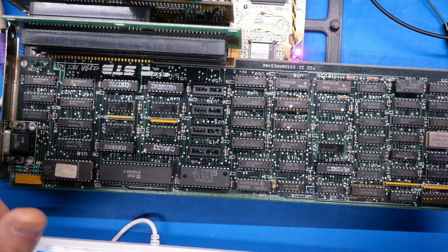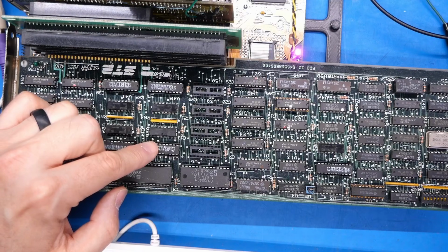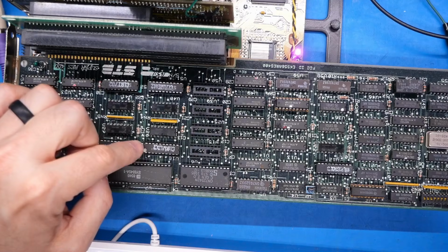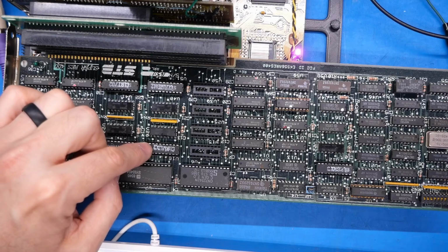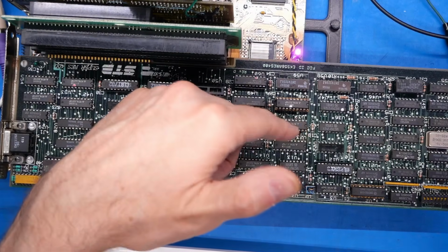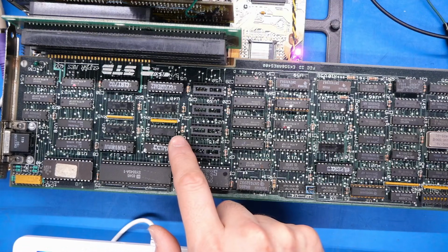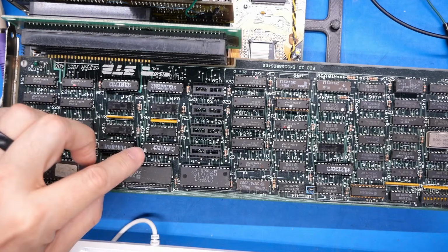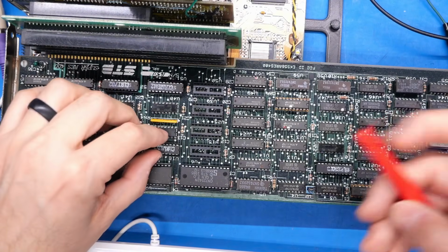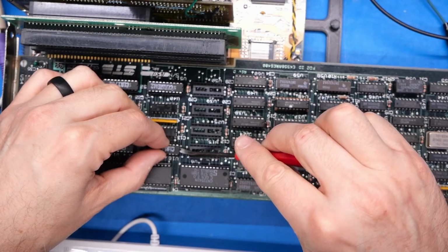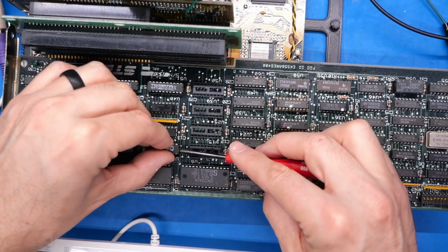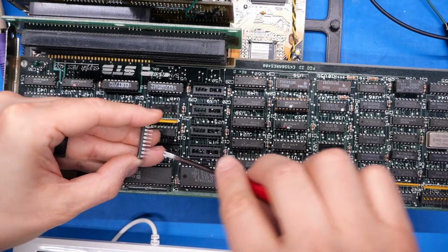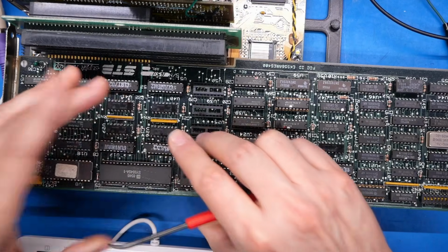Now, what has me worried here is that the PAL chip here, which we know this pin is also getting that weird clock signal. Is this somehow an output that's forcing that clock signal onto that signal? I can't quite make out what kind of chip this is, but all I can think to do here is pull this out of the board and bend that pin out, since this is in a socket. And then we can see if that has any kind of an effect on the overall system. So I'm just going to lift this pin out here, just like that, and put this back in the board.